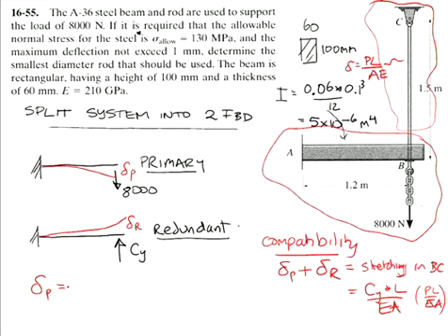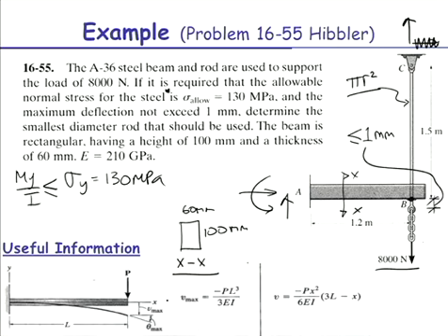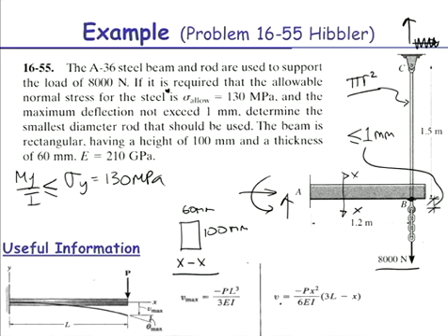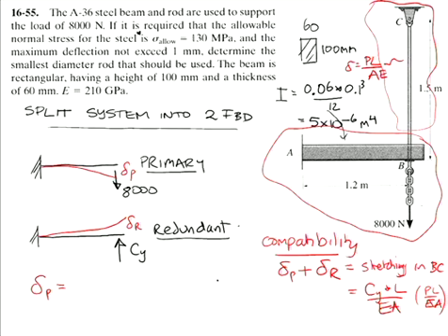So, what is our primary deflection equal to? If we do go back now to this useful information, where do we want the deflection? Here you'll see we want it where the load is applied. So which formula would we use, A or B? A, cool. So we're going to use this equation here, which tells us the deflection under the point load. So thus, in here, our deflection, it's downwards.